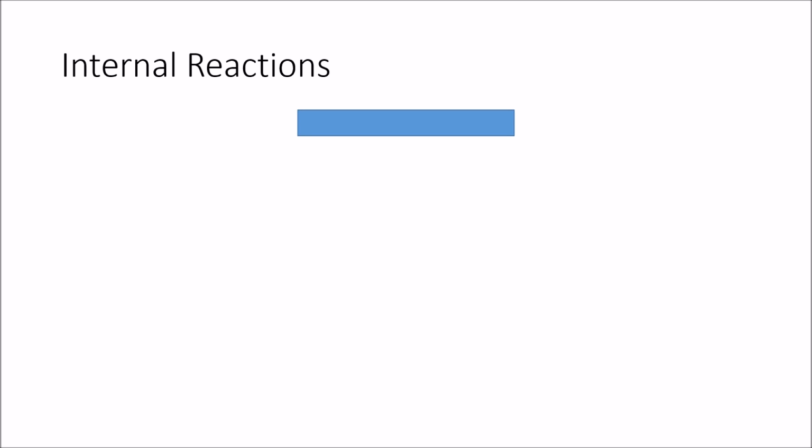The point I want to make is that when you make a cut in your member like this, you'll be left with 3 reactions. First, you will be left with the axial reaction, which we will call the normal force, and then a vertical force that we call the shear force, and the moment reaction. It should be noticed that these are the same reactions that you will see in a fixed wall support. We can also mirror these reactions and see them as opposites on the other side. If you were to put these two pieces back together, they would cancel each other out.